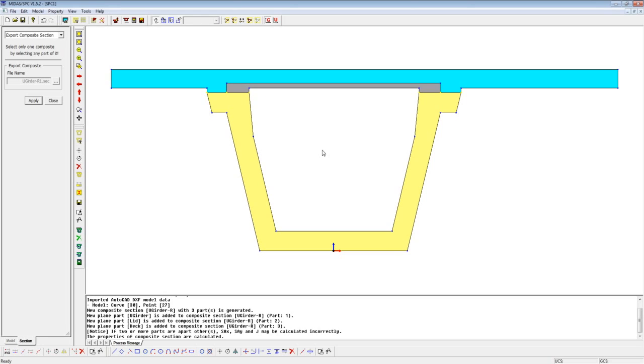And to consider the haunch, if you really want to consider its load and you want to be accurate in the dead load effects, then you can consider the weight of that haunch onto the structure as well. So in that manner, you can consider the variable cross-sectional properties due to the different haunch heights. It is hard to find a platform or a spreadsheet that will consider all those variations.